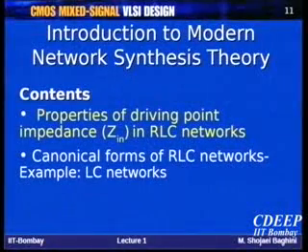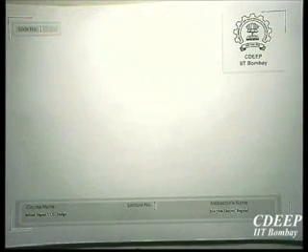So now I will switch to this. First is a review of continuous time filters. Why do we need continuous time filters or analog filters? Because all signals from nature are analog. Therefore, to capture signals from nature, we need to have an analog platform. But there are many problems with these signals in nature. These signals are mixed with noise. These signals have a limited frequency band. These signals are not very high. And there are always different types of interference on these signals.